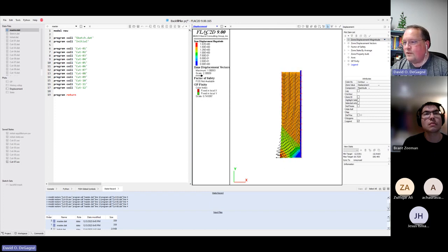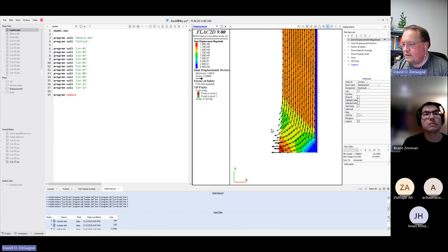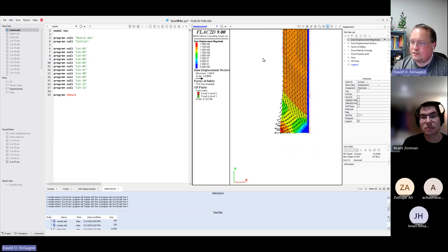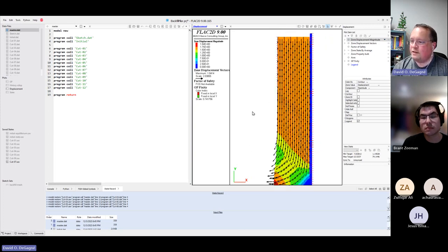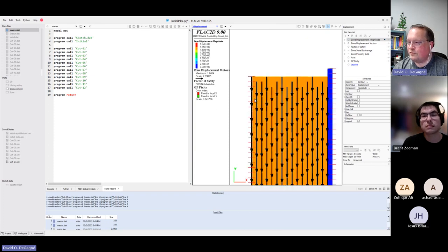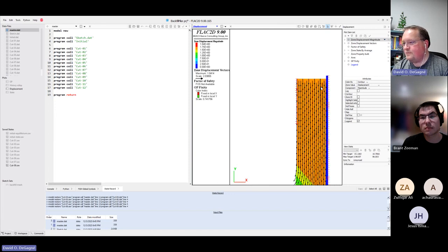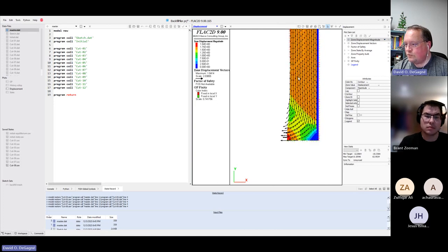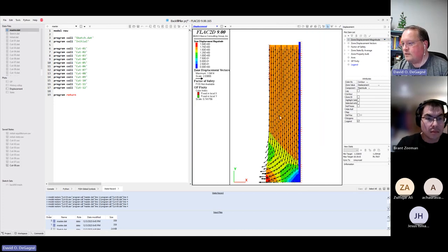And you can see here that we're already getting 1.6, 1.7 meters of displacement, which isn't terribly encouraging because this is 15 meters. So probably the initial template cohesion is not high enough to solve your problem. Also note that this was originally at this height, and so through this process, the backfill is already kind of compacted and displaced that vertical distance, in addition to the displacements that's happening here along the face.